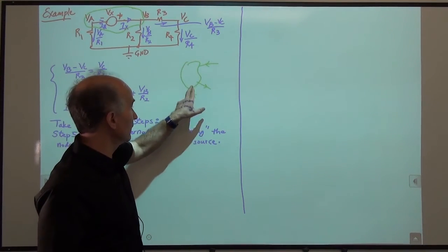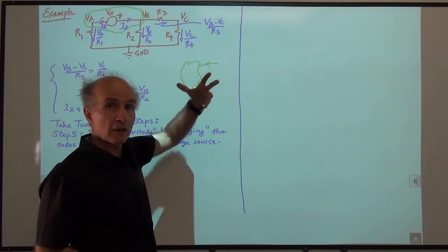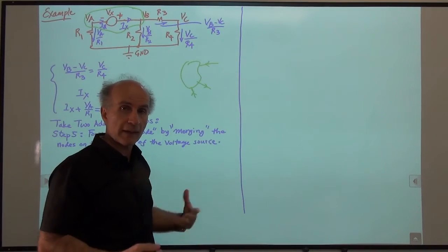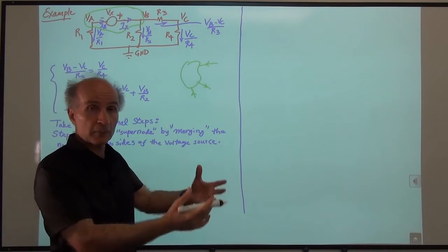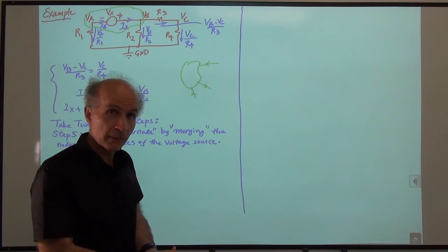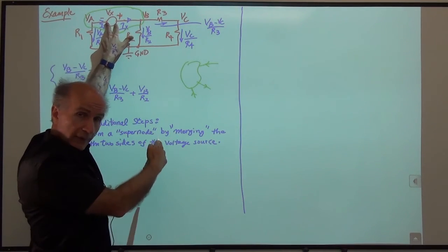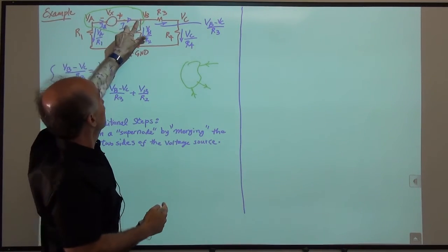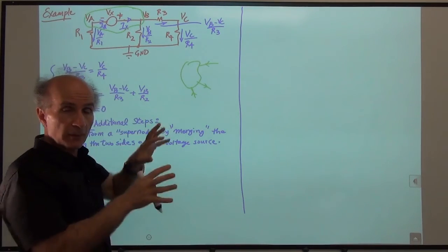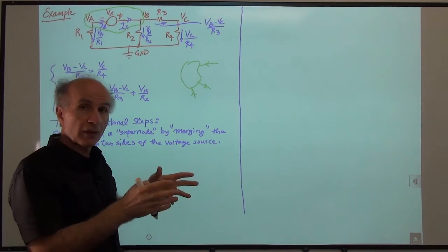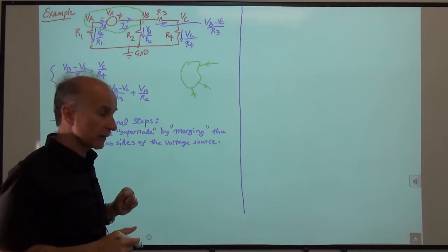If you have cars coming in and cars going out, the sum of all these currents or flow of cars has to be zero, because cars cannot disappear in the intersection, or be created in the intersection. So we will put the voltage source, which is causing trouble for us, and its two nodes in one box. And now this box has a bunch of wires coming out of it. We're going to write a KCL for that box, not for the voltage source anymore.